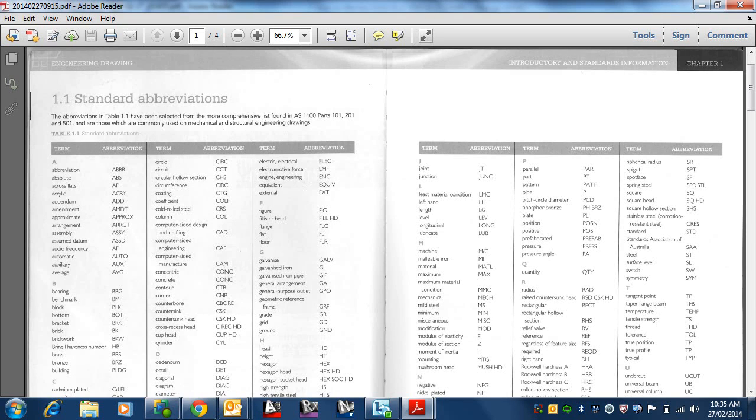I was hoping to have it updated so it shows that you're able to set up your line weights within your layer command, which is a bit more natural, and a lot of you would have already seen that by just bringing up the layer dialog box. The book actually talks about setting up the line weights in some other hidden system within the plot dialog box, which is a little bit of an old-fashioned way of doing it. But anyhow, I'll help you through that when you come to printing.